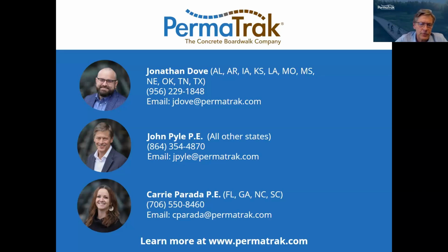Some of the limitations around top down: as I tried to mention, it does limit how far you can span if you're doing truly fully top down construction, based on the size of the equipment that you can fit on top of the boardwalk and then reach out. Generally 10 to 12 feet is going to be your maximum. The foundation type is limited as well. Top down lends itself very well to using a helical pier, but the geotechnical conditions may not support the use of a helical pier. It could be rocky soils.